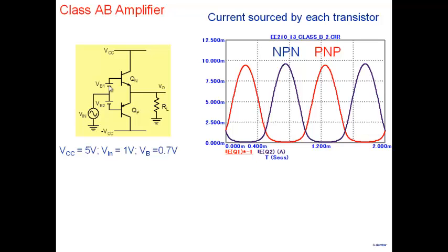Because note that what would happen is, we said that this battery keeps the transistor on even when you don't apply any input. It keeps it at the threshold of conduction, so current is flowing. So when you apply the positive cycle, obviously the transistor conducts even more. But when you go to the negative cycle, it takes a little bit of negative voltage before this Q1 turns off.